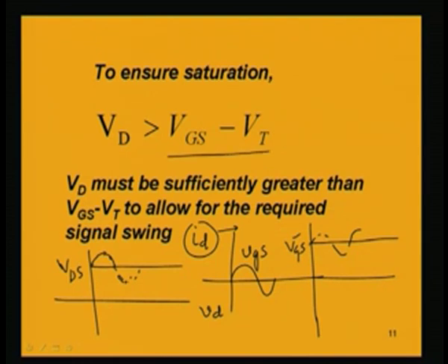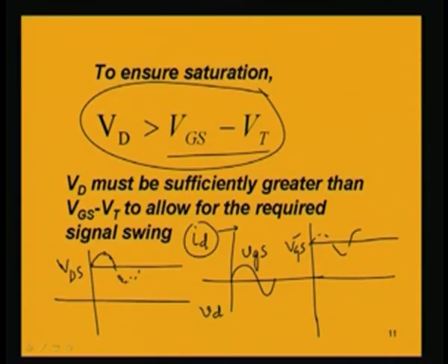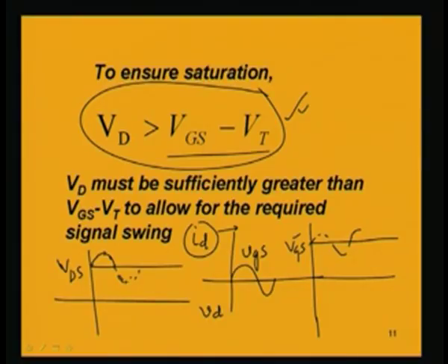That has to be kept in mind, because we are dealing with amplification, we know that the output voltage will be greater, it will have a high magnitude. So, the biasing should be proper there, so that under no condition this is violated. As we have seen in BJT, at no point should it go to cutoff or saturation, it should always be in the active region, so that the emitter-base junction is forward biased and the collector-base junction is reverse biased. That has to be maintained always. Similarly, in MOSFET, this condition has to be satisfied for the enhancement type of MOSFET we are dealing with, so that it is always in the saturation region, because the MOSFET amplifier operates in the saturation region.